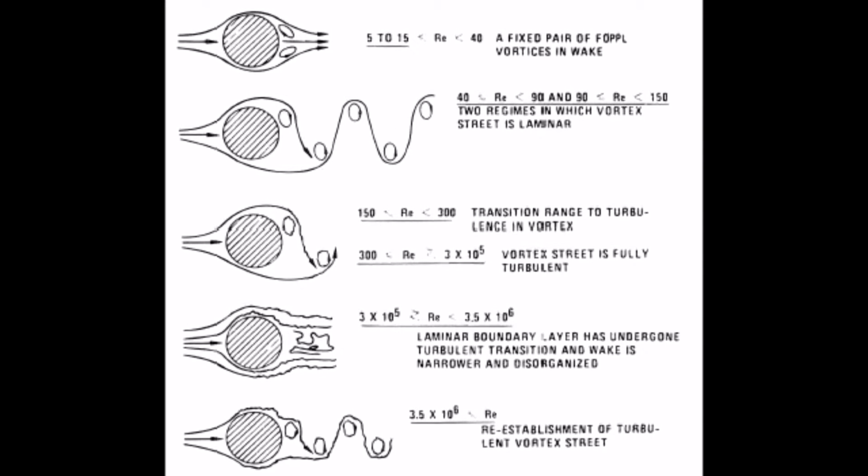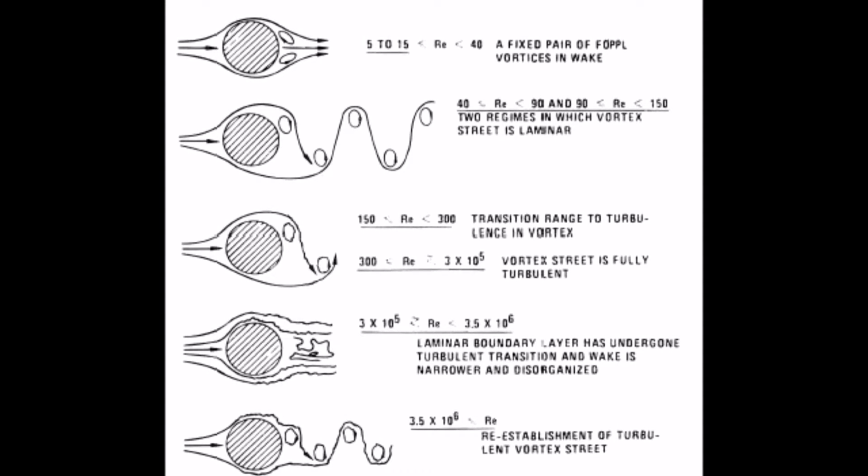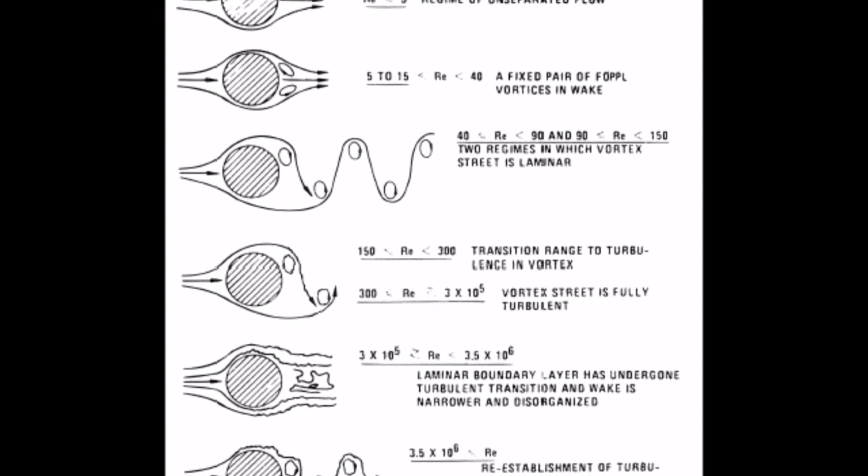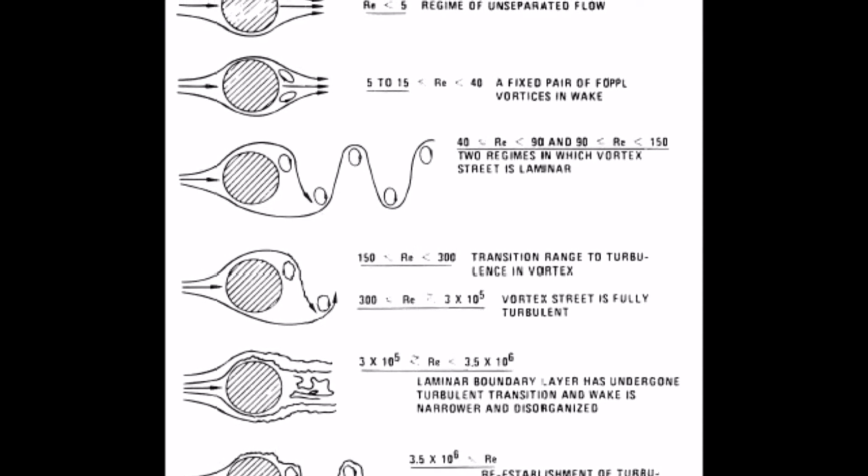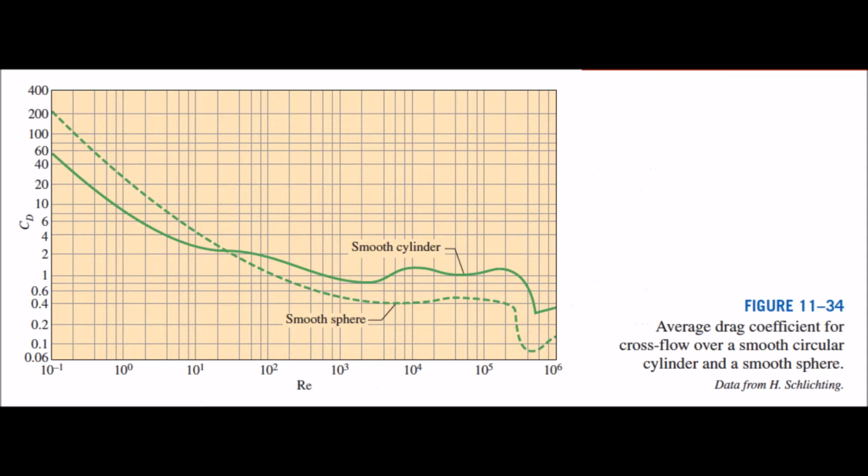In this lab, the wind tunnel is used to examine the flow around the cylinder body. The once uniform flow is obstructed as it passes the cylinder, causing vortices and pressure deviations around the cylinder. At significant Reynolds numbers, the drag caused by a cylinder in flow is primarily caused by pressure deviations, as flow separates from the surface of the object. This can also be called pressure drag.